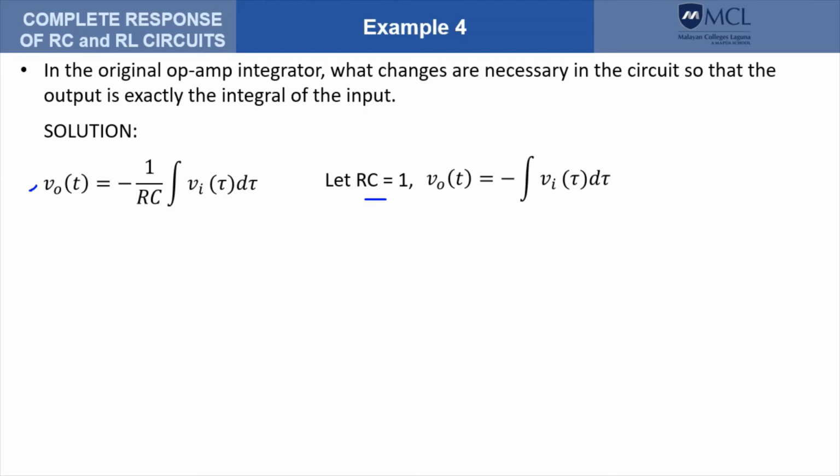So that means that C must be equal to 1 over R numerically. And that will give us this result. However, the result is still not the integral of the input because of the presence of the negative sign. We can get rid of that by passing the output of the